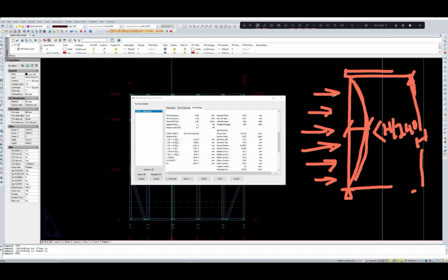Now when we calculate this deflection, we should apply 0.7 design pressure PD instead of 100% pressure. So this 30% reduction in this local lateral deflection is due to the presence of the sheathing on both sides of the stud.